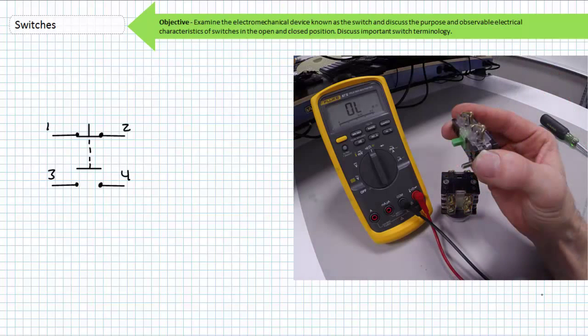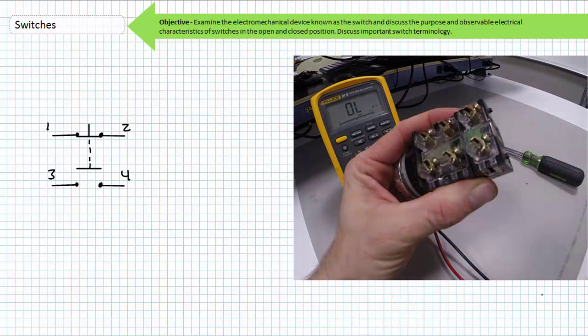If I wanted to add a third switch to this same package, actuated by the same push button, one can use something called an auxiliary. Notice the green plastic plunger. This is the mechanical interlock mechanism used by the push button on the front to activate this additional set of contacts while maintaining electrical isolation. This particular auxiliary simply screws onto the back of the switch package and the plastic plunger slips into a well. This additional switch could again be used to control a complex system.